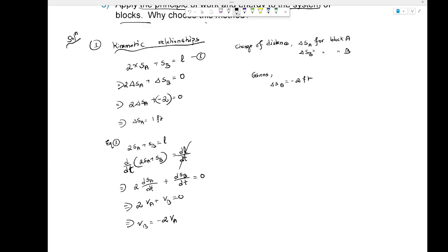You see, the question does have 3 steps. The second step would be drawing the free body diagram. Now, when I'm saying drawing the free body diagram, you should be drawing 2 blocks with all the forces involved on that. What are the forces? Like the weight, the friction, whatever, right? The tension force due to the rope that is attached to the pulley. Let's do that. Try at least the free body diagram of those two blocks. Take your time to finish this as well.